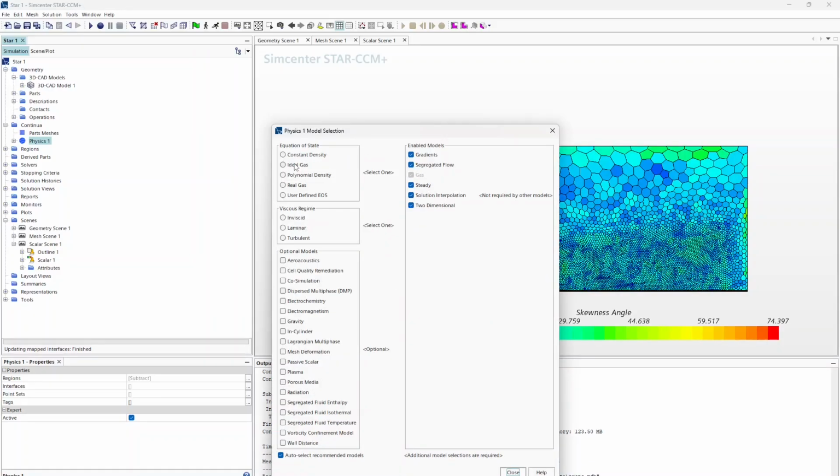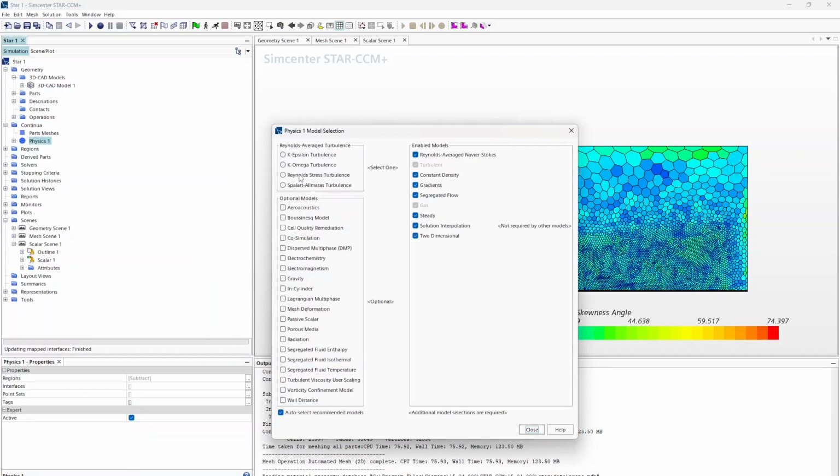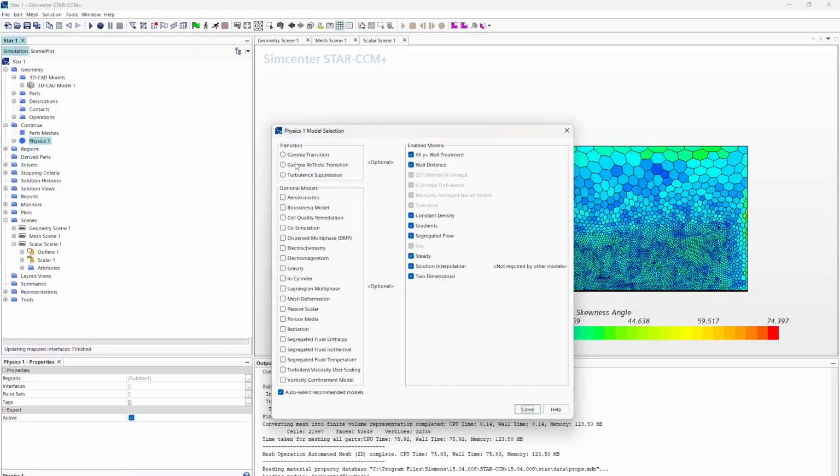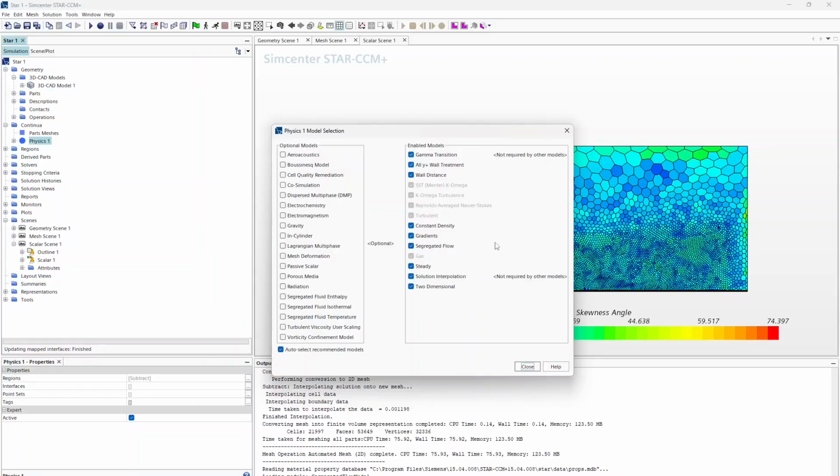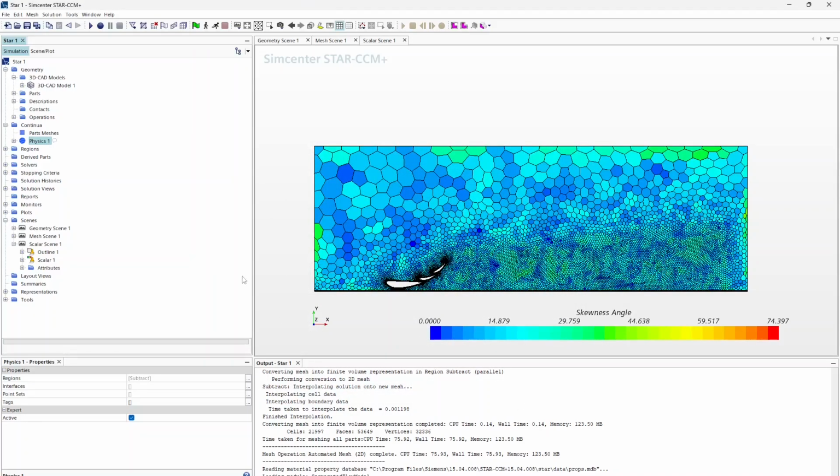Coupled flows are great for turbomachinery applications, as they take fewer iterations and solve the Navier-Stokes equations together. For pressure and velocity, segregated will solve for them separately, and in response it'll take more iterations, but it solves way faster. And we have a constant density because we are below 0.3 of the Mach speed of air, and we're going to assume turbulent flow. For this model, we'll choose k omega and do the gamma transition. I have a Notion article written about the differences between the different turbulence models. You can consult that. It's too in-depth for this tutorial. We're trying to keep it as fast as we can.